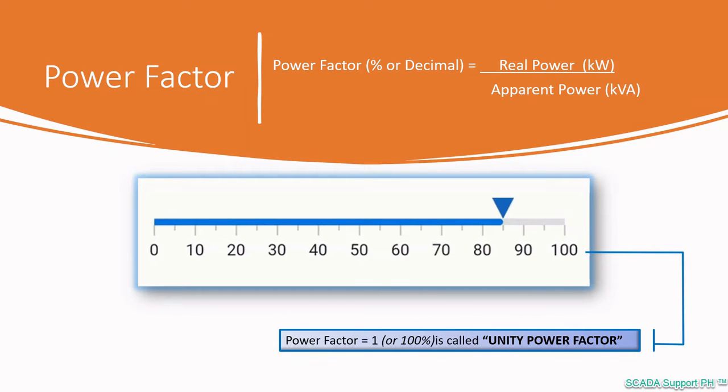A poor power factor with a value towards 0 will produce more reactive power, which we consider as wasted power, reducing the efficiency of the circuit, while a system with a power factor closer to 1 or unity will be more efficient. This is because a circuit with a low power factor requires more current than the same circuit with the power factor closing to 1 or unity.